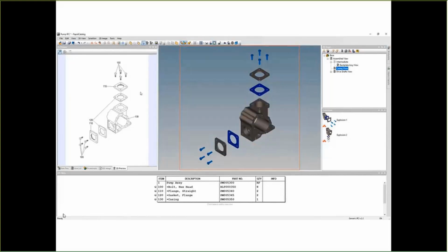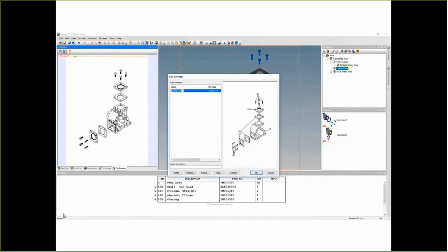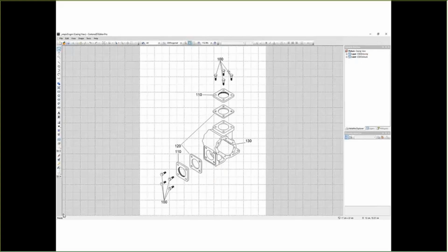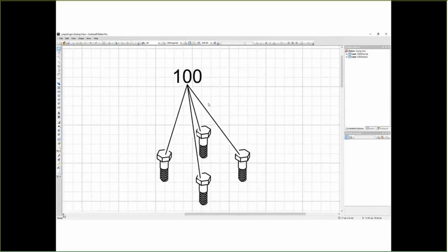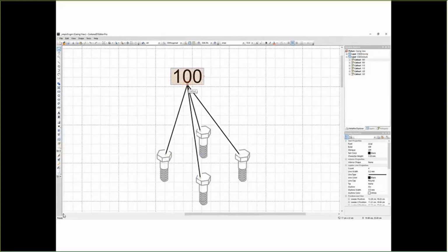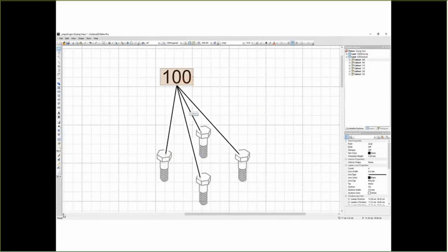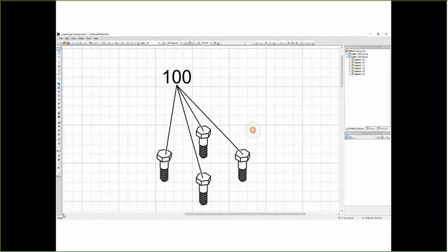What this will do is create an additional layer of white spacing between the 3D model and the leader line of the callout. In some standards, this is a requirement for every callout placed on a 3D model in a 2D image. You can also specify the parameter at any time in the property inspector if you wish to change the settings of the halo effect.